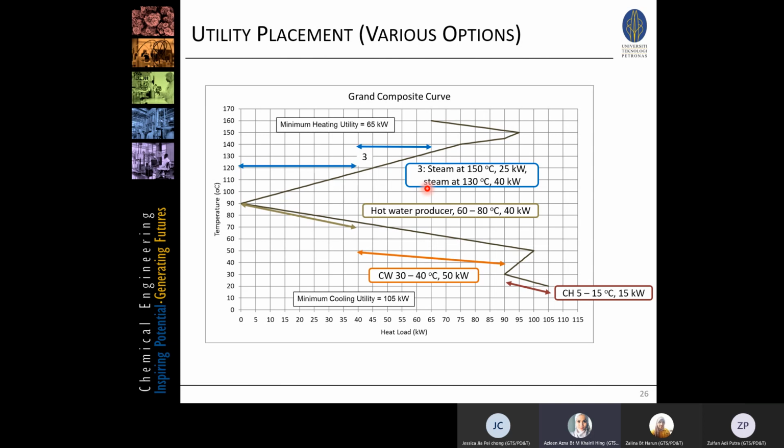It's an option lah whether you want to use refrigerant ke, nak pakai cooling water ke. Yeah, basically we need depending on this temperature as well ya. Kadang-kadang ya, this temperature is quite high. We can also generate steam here, by cooling down 90. Say for example, this pinch is not 90, but this pinch is 130 for example ya.